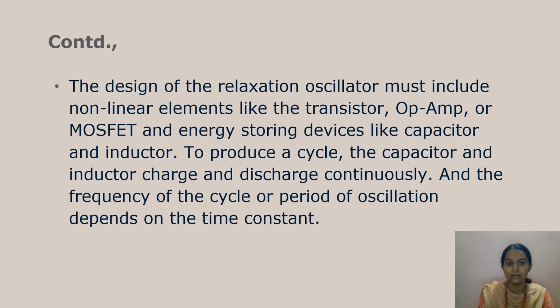The design of a relaxation oscillator must include nonlinear elements like transistor, op-amp, MOSFET, and energy storing devices like capacitor or inductor. To produce a cycle, the capacitor and inductor charge and discharge continuously, and the frequency of the cycle, or the period of oscillation, depends on the time constant.